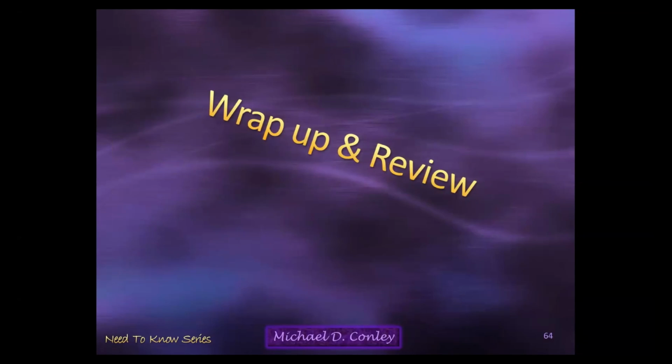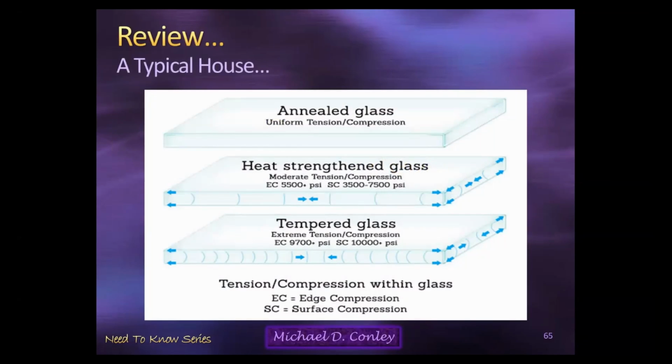Wrap up and review. The type of glass we're typically going to find in a house is going to be annealed glass. Heat strengthened glass has moderate tension and compressive strength. Tempered glass we find more and more often in the homes today. Extreme tension and compression capabilities. And when we're dealing with any one of these panes, or the bottom two rather, we have edge compression and surface compression. Those two have to be in balance, which is where the heat process comes in. Otherwise, the pane of glass will shatter or break over, if not immediately, over time.